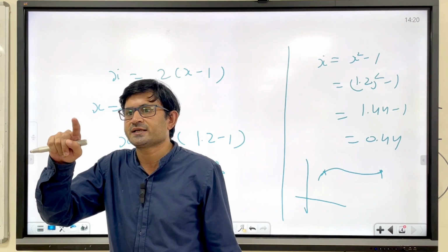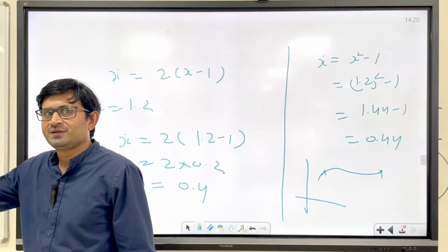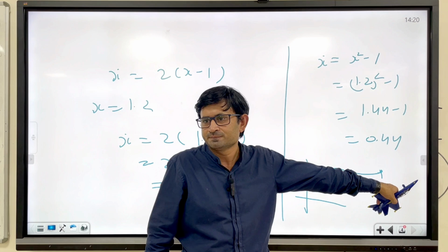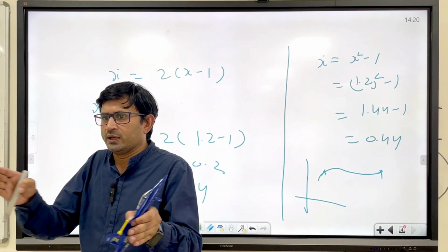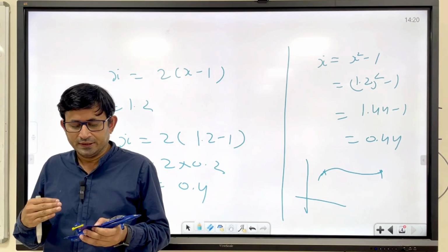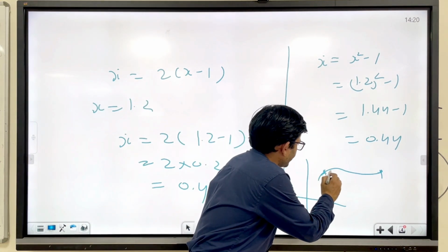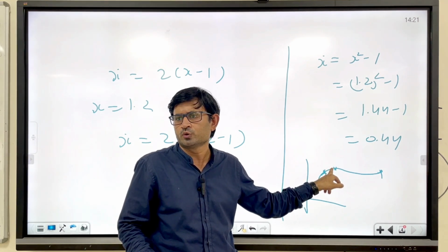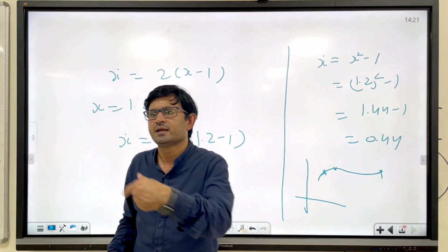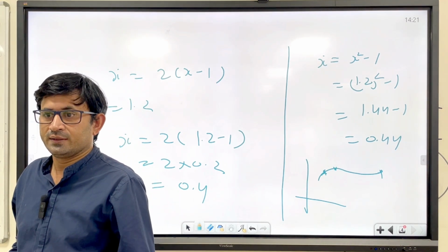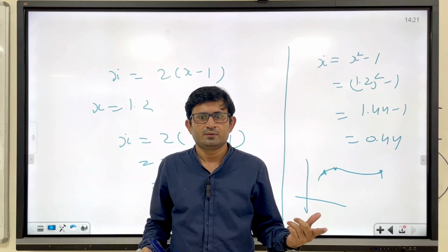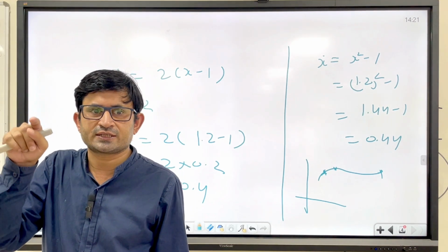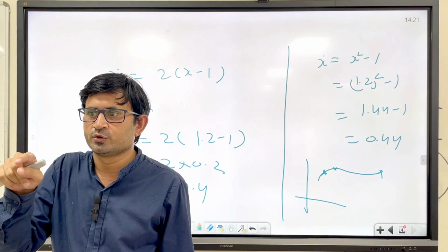But there is also a solution. You can linearize at multiple trim points. Like you have linearized at this trim point, you can linearize at this trim point. So many trim points you can linearize, and when you think this trim point and this trim point are falling in the linear domain, then there is absolutely no problem to linearize at this trim point. You can use interpolation. So where you think the nonlinearity is coming more, there you have to linearize.